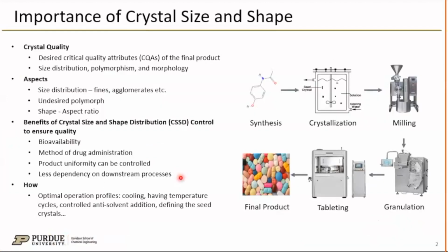Crystallization is the particle formation and purification step of active pharmaceutical ingredients in almost all the pharmaceutical processes. Here is depicted a typical tablet production process with the crystallization step highlighted to show its importance for us. Experience shows that the properties of the crystals produced here affect the downstream processes such as filtration, milling, or tableting, and the bioavailability of the drugs.